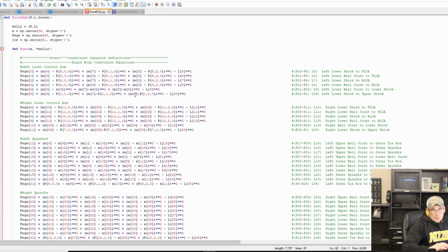And so what we're using in this process is a system called multibody dynamics or multibody kinematics. And when you set up equations using that approach, the first step is to set up the rigid body constraints. And really that's what we were doing with all of those local points: we were defining the shape of the bodies that were in our system.